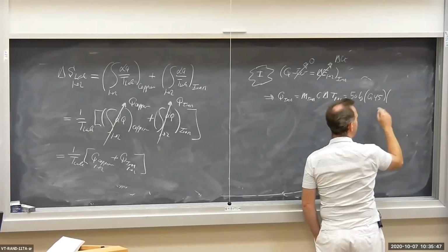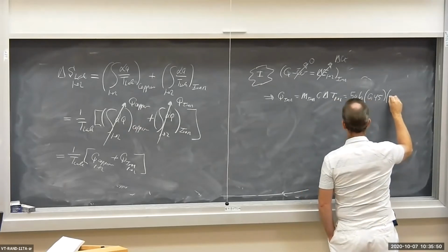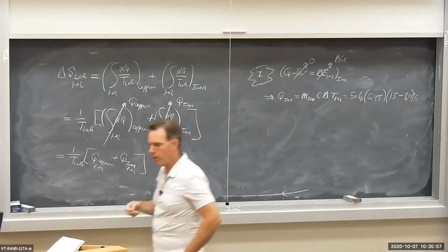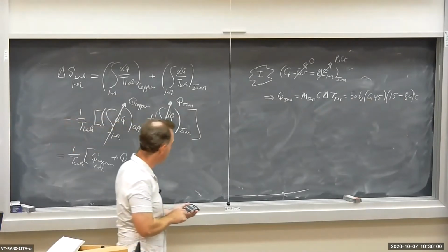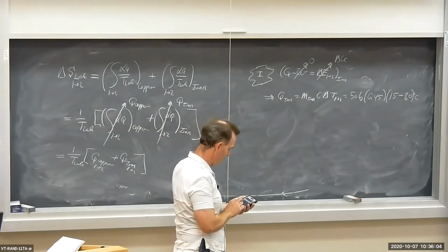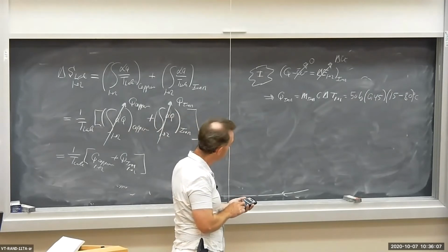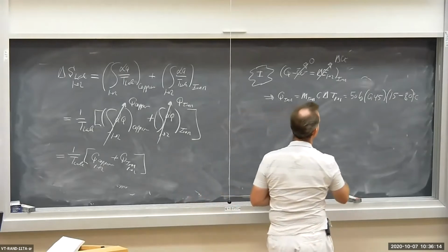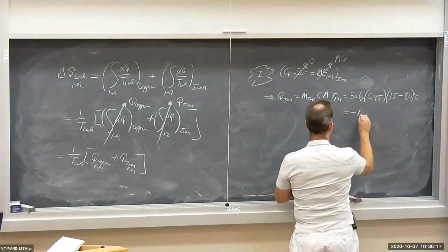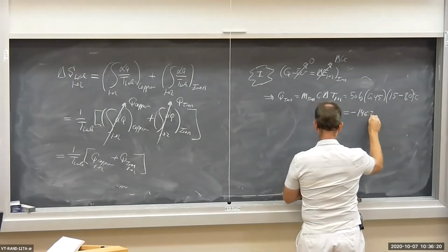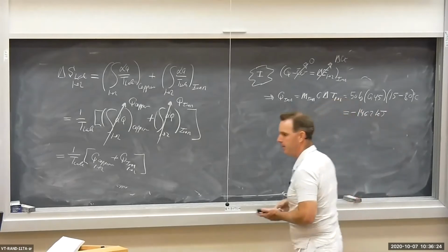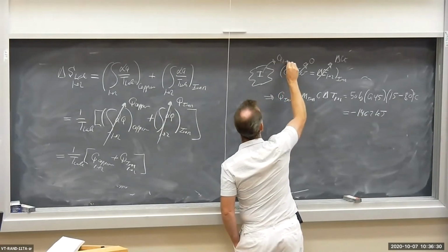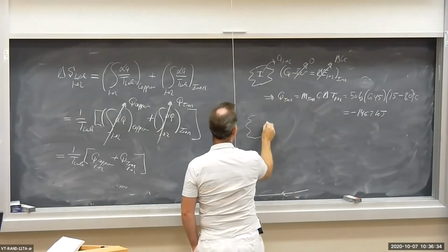0.45. And the temperature change was 15 minus 80 degrees C. Okay? So let's crank that out. 50 times 0.45 times 80 minus 15. And I get minus 146.2 kilojoules. So we're rejecting heat from the iron, Q1 to 2. Same thing for the copper.